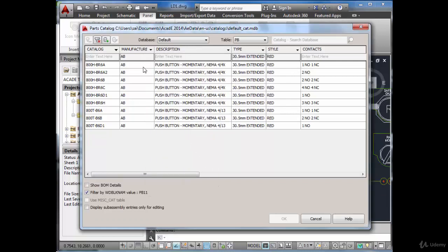But while installing your AutoCAD in your PC, it will ask you to select all the manufacturers. You can select all. It depends on the capacity of your hard disk. It will take more space, and while inserting and cross-checking, it will take that much time too, because it has to search all the database. So just to avoid that delay, I have chosen only one make here.